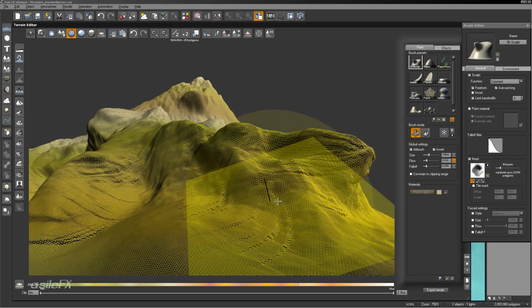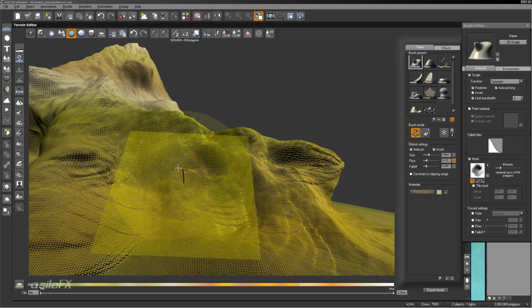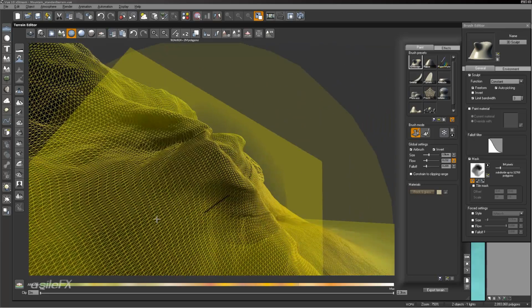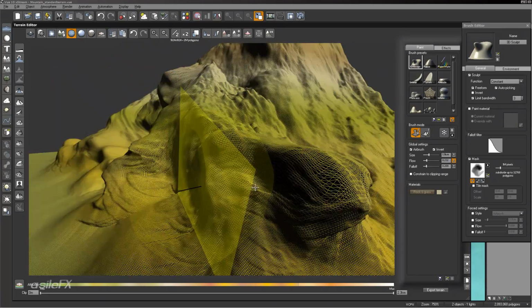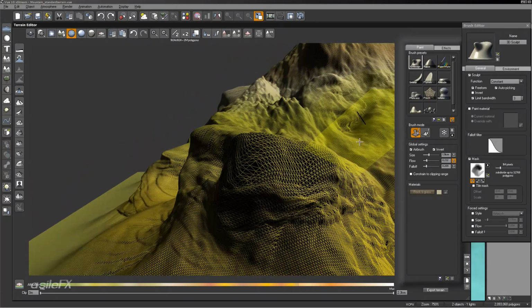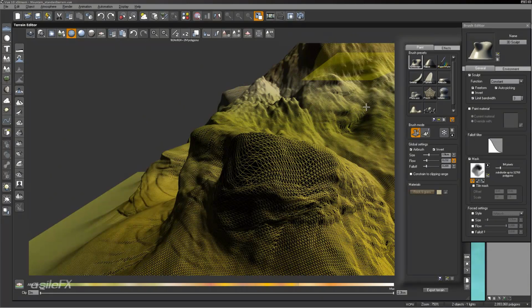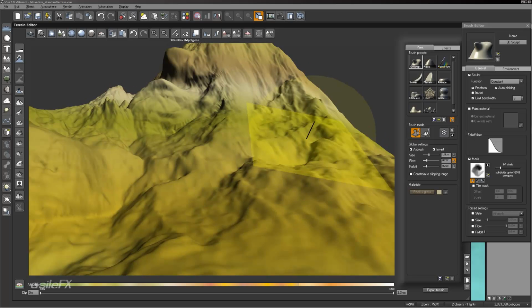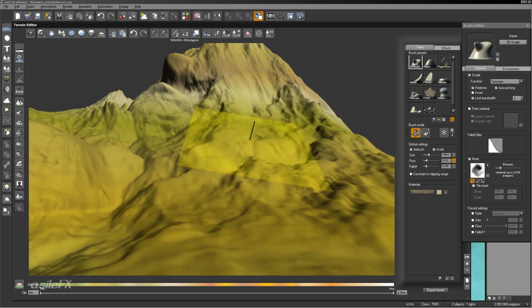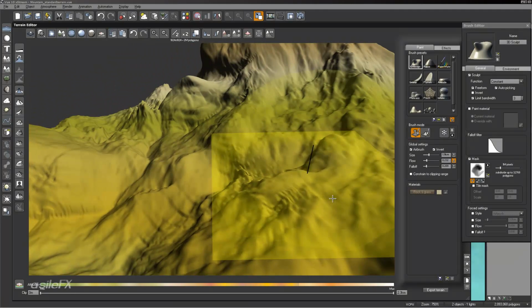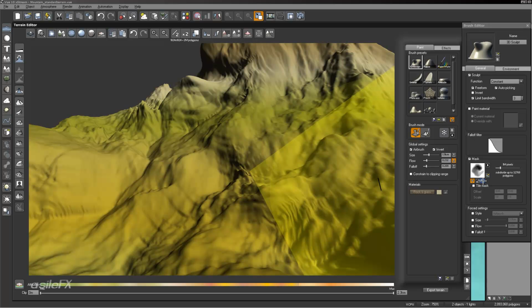One of the best ways to invert is to invert the image for the mask and then invert the actual brush. And that's one of the best ways to get the detail out of it. Because the falloff is still going around the edge properly then, and you can still get the right details. Depending on the resolution and the quality of your video card, once you start getting up to 20, 30 million polygons, the wireframe mode is pretty heavy on resources.